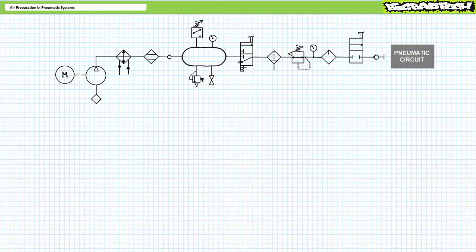Most likely the circuit will work as intended for a couple strokes as the reservoir's stored pneumatic energy is bled down and down. However, it's not going to recharge as intended since the pressure switch's set value has been erroneously adjusted too low. Over time, valves and actuators in this circuit will experience less and less pressure and resultant force as the pneumatic energy stored in the receiver eventually exhausts itself, with the period of time being dependent upon the size of the reservoir and the quantity of stored pneumatic energy in it. The point being, a regulator only regulates downwards.